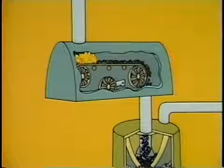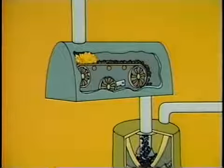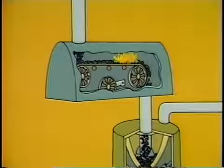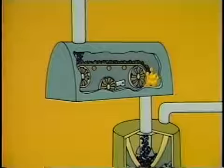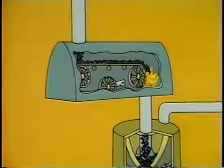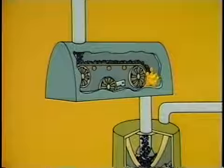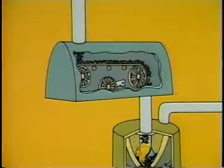As with bunker fires, the most common action taken by an operator to handle feeder fires is to increase the flow of coal through the feeder. The idea is to transport the coal to the burners as rapidly as possible. In some cases, increasing the flow rate through the feeder will eliminate air pockets and smother the fire. In other cases, the fire will simply move from the feeder to the pulverizer.